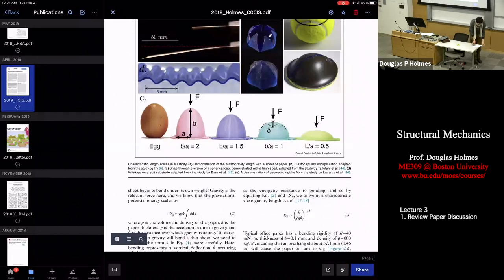If you just simply curve it like a cylinder, I'm just going to take the ends of my sheet and warp it up just a tiny, tiny bit. This thing is remarkably stiff now. It doesn't sag. If I put my fingers down, it drops. This is Gauss's Theorema Egregium. This is the exact same thing. Why? Well, this thing is flat. It wants to bend. It's incredibly cheap to bend this way. However, if I add a little bit of curvature to it,